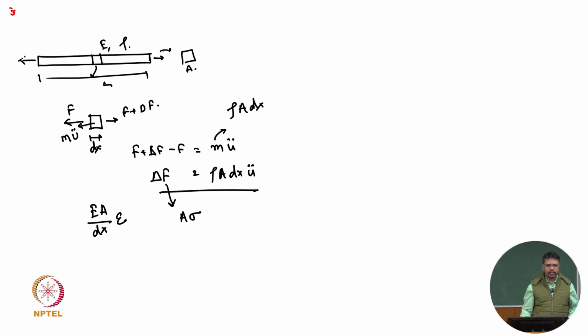Agreed? Area into stress. So what is stress? Stress will be nothing but Young modulus into strain. What is strain? That will be del u del x. So that will be EA into del u del x.